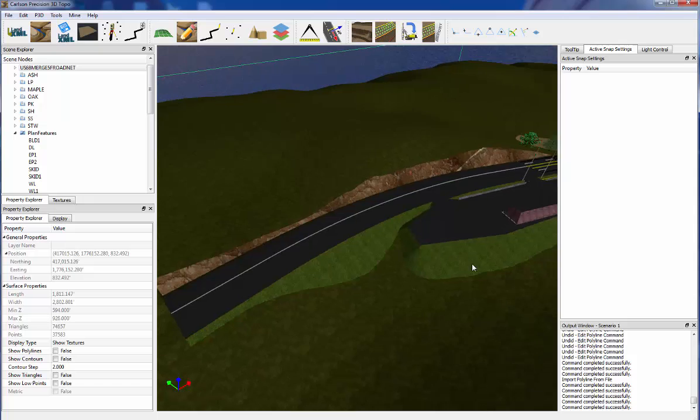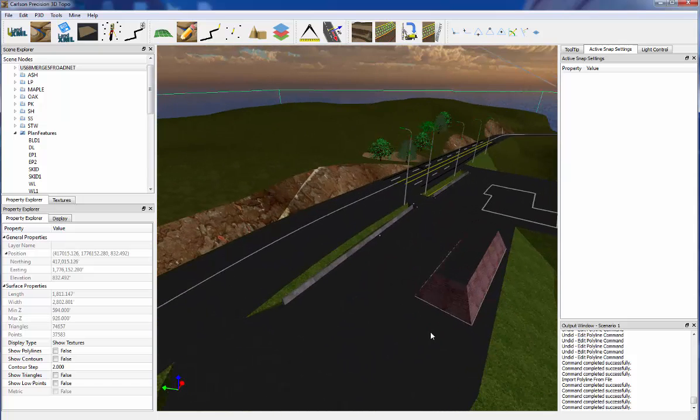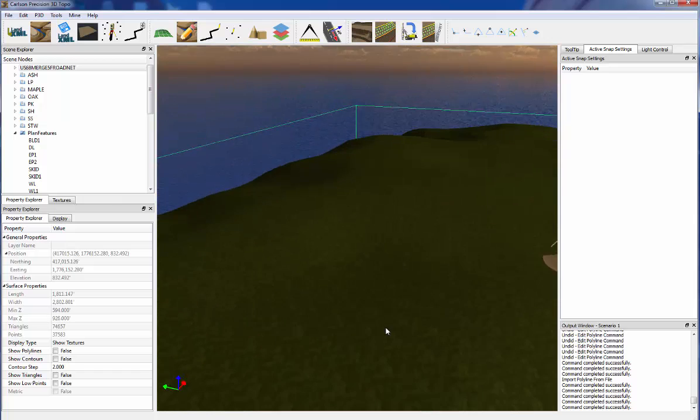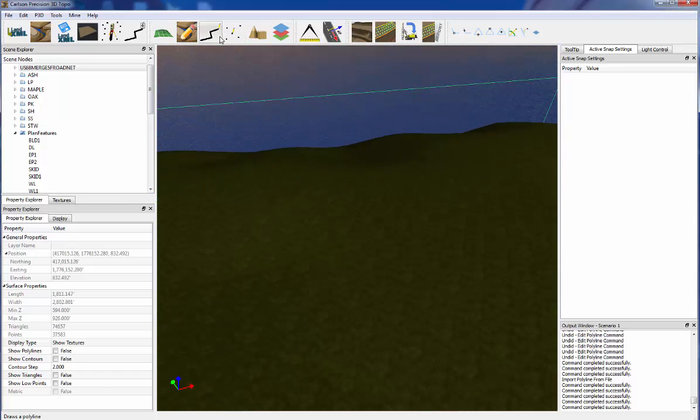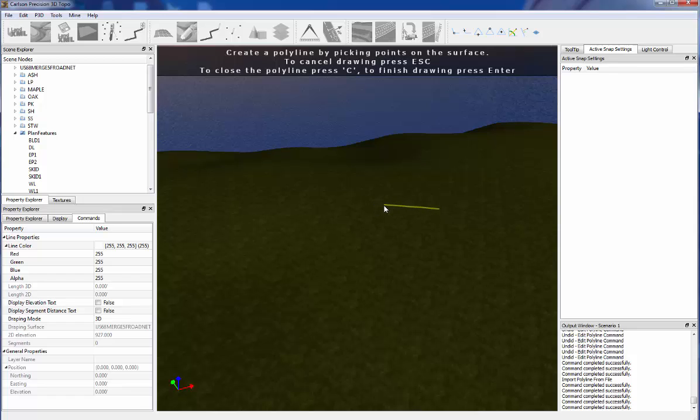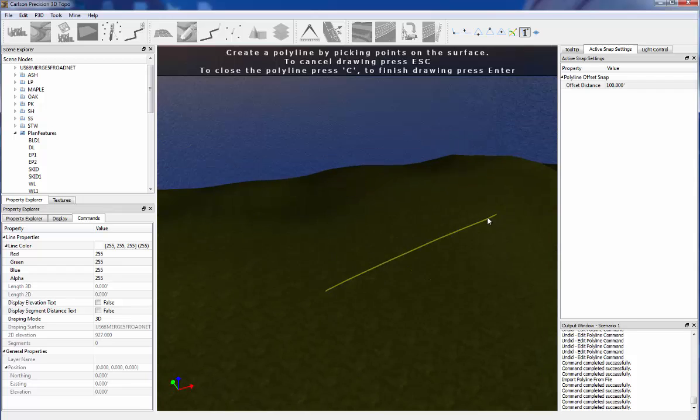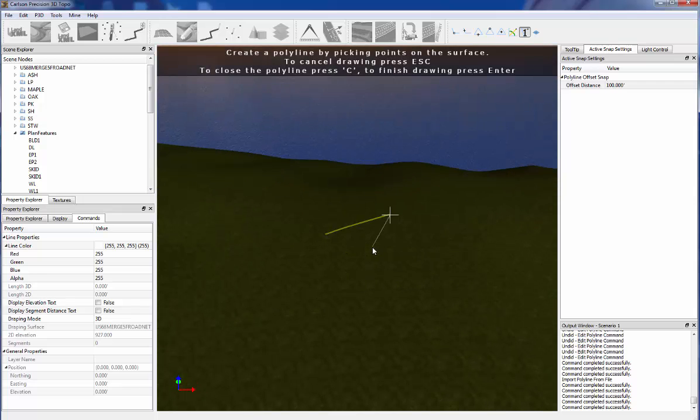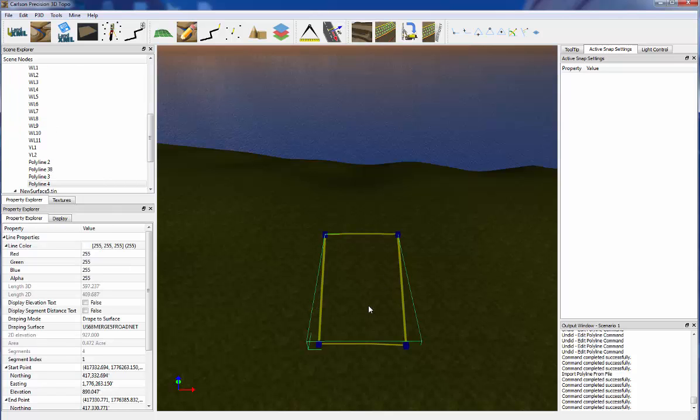All right, so we should do the merge surfaces, pad templates. Yes, so in our pad template routine now, we can take any polyline, and so if I wanted to create a polyline that is in increments of 100 feet. I'm just going to draw a rough polyline here.